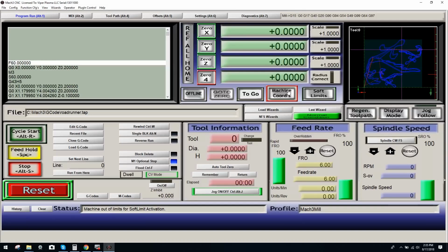What we want to validate now after doing that is clicking machine coordinates, and you can see now that our G54 offset is still representing these positive integers. It's carried it over because it took all of those integers and said, okay, we're going to shift now and say this is your end stop position, but this is the real measurement you are under this offset. It's going to carry those integers over to whatever offset you're on whenever you do a ref all.